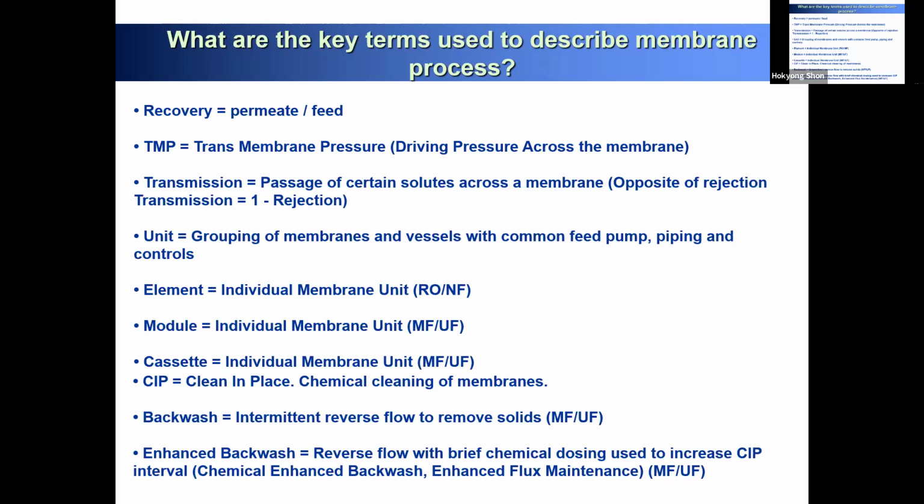Backwashing is intermittent reverse flow to remove solids. Also, enhanced backwash is reverse flow with a brief chemical loading, used to increase the CIP interval and enhance flux maintenance.